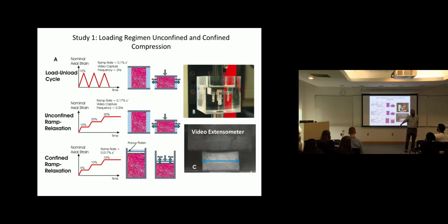If the material were linear elastic, what would the stress here look like? That's what I'm going to plot next. What would it look like? Simple answer, right? It's a linear material. A triangular pulse has to be triangular also. The slope will depend on elasticity. But let's see what this material is going to do.